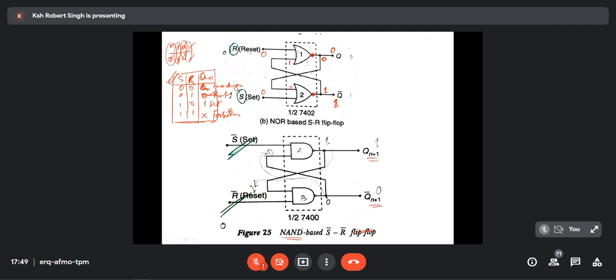Now let us think, 1 and 0 is 1, bubble gives 0. Another one is also coming, 0. The next state is 0. Here also 0 and 0, which is 0, bubble gives 1. 1 is also coming again. So it keeps on coming 0, 1, 0, 1. It will always be stuck at 0 and 1. That means the output never changes. The previous output was 0 and 1, and it stays stuck at 0 and 1 always. So the output never changes. Can you understand what I'm saying?